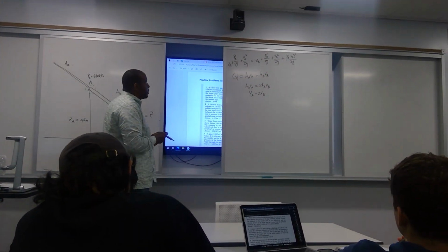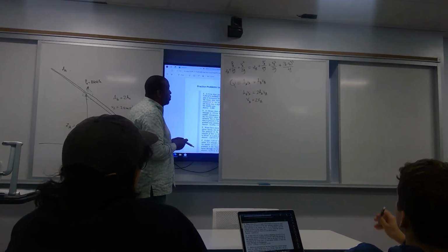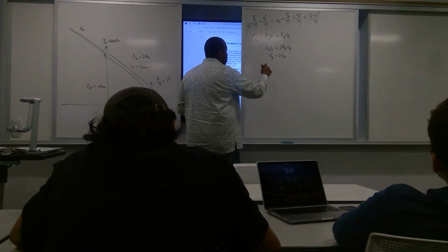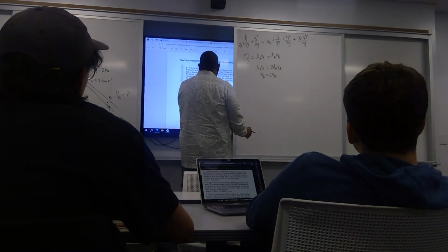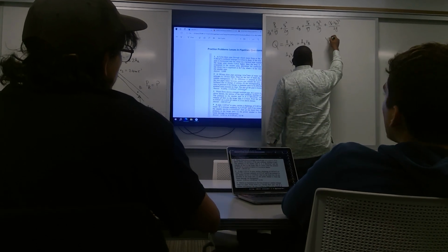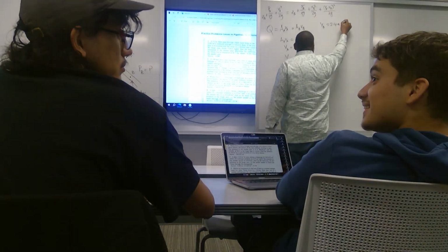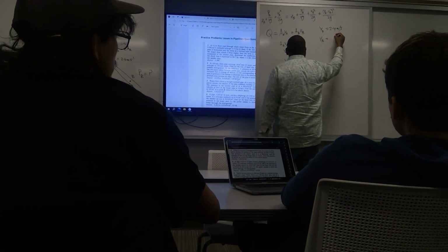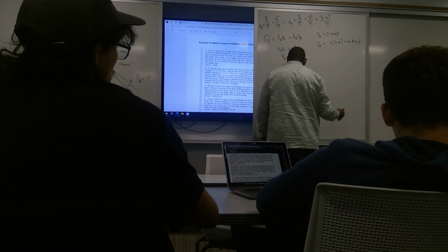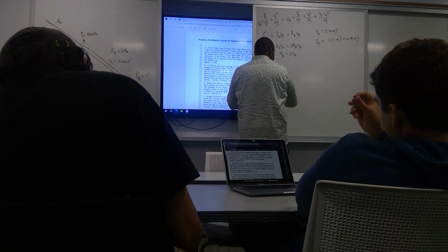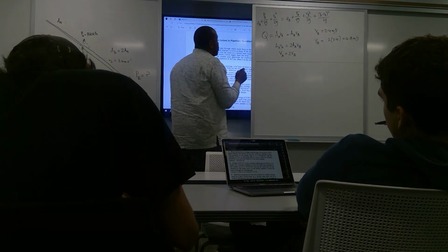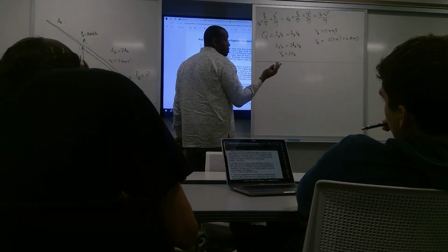Right, I can replace, because they gave us VB. They told us VB was 2.4 meters per second, therefore VA will be 2 times 2.4, which is 4.8 meters per second. Yes? So we're in business. We have our VA, we have our VB, so now I can start solving for PB.